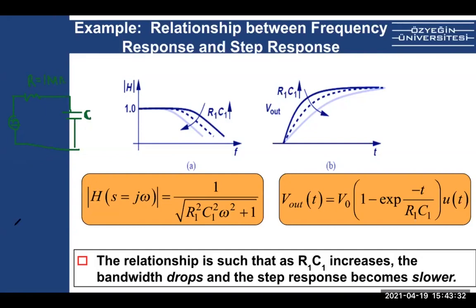How does the capacitance charge? Is it charging like this or would it be charged like this? The second graph. It would be charging like this, right? Because this R causes the current to be so small. And because current is so small, the charges on this cap would take forever to collect, Q equals CV, right?